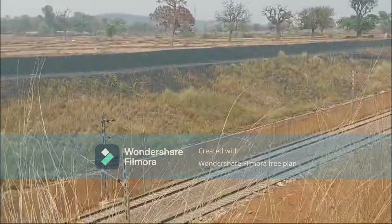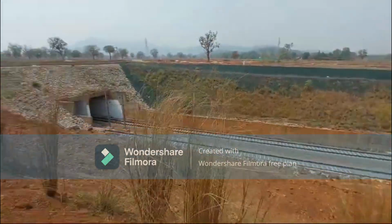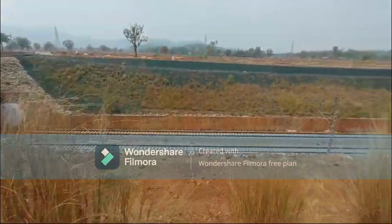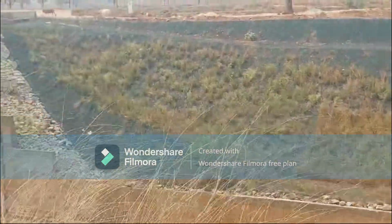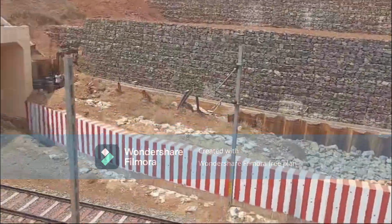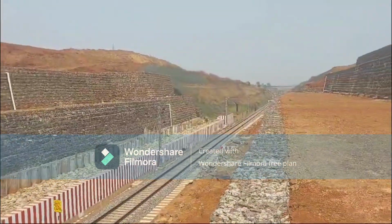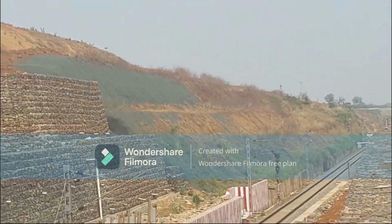constructed with geomat and grass turfing, and here erosion control and stability. Also here the stone pitching has been provided, and the vegetation is geosynthetic. Here a railway line is constructed in a hill area. You can see here a gabion wall provided for slope stability, and slope stability is also provided with geomat with